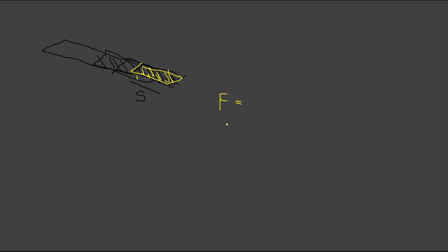So that's going to be, you need the shear stress. So this is a stress, VQ over IB. So this is B, okay? You have to multiply. So you need to convert this to a force. So this area is S into B, right? So then B is getting cancelled, right?